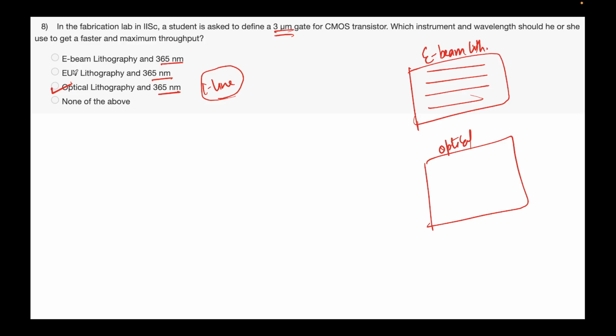We have talked about deposition. Now, what do we mean by etching? Again, I'll draw the same. So we have this area protected by a mask, and I want to etch this silicon dioxide. So this is your mask. I want to etch. So if I expose it to chemicals, again this is similar to what we talked about in doping. The chemicals will come here, whatever the etchant is, and they don't care. They'll etch in this direction, this direction, this direction. Right, what you get is a profile again like this, an isotropic etch.